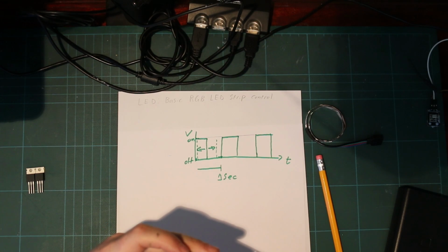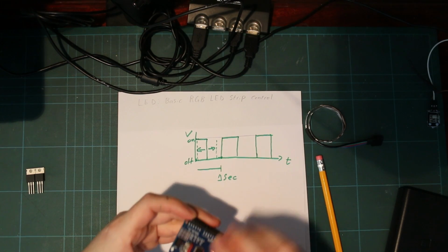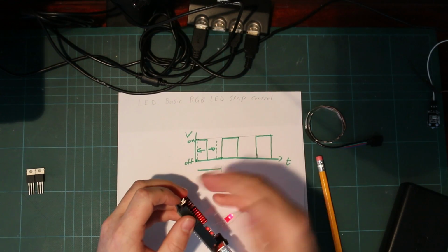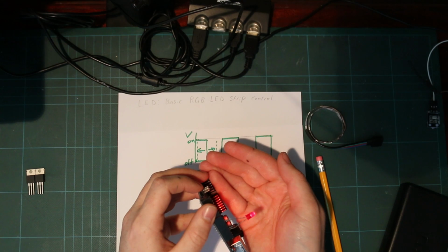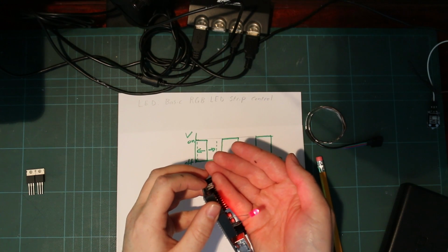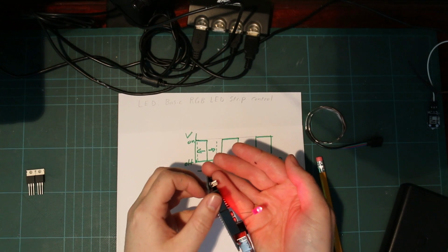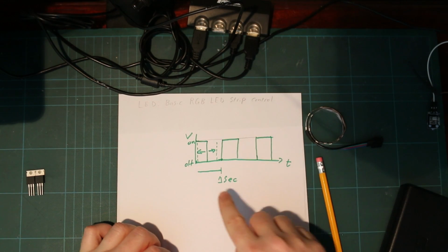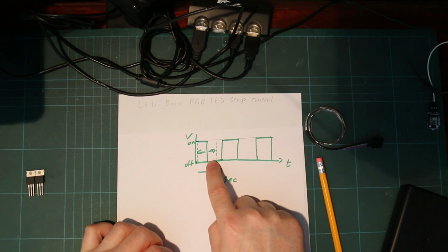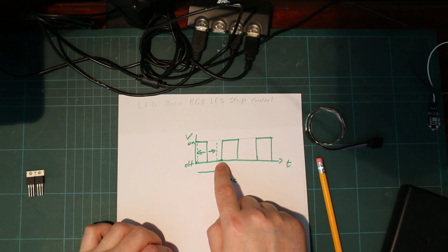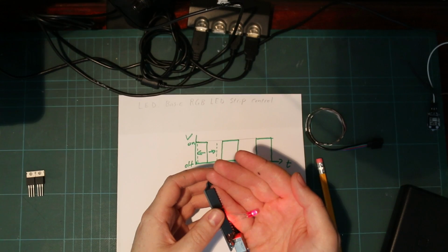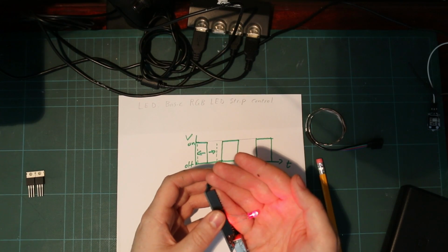And if I've done this correctly, then you see there, we have our LED turning on and off periodically. And all I'm doing in this little sketch is what I mentioned here, where I'm just increasing the amount of time it's on and then decreasing the amount of time it's on. The resulting effect is an LED that we can control the brightness on.